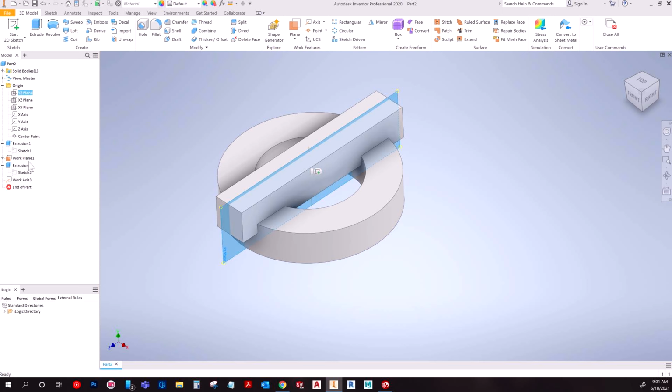If you intend a part to potentially change the position like that, it is good to have a work plane. It's actually the only really ideal way to locate a feature without something having to be redrawn, is to use work plane. So there is a use case. It's just finding how you can fit it into what you're doing.